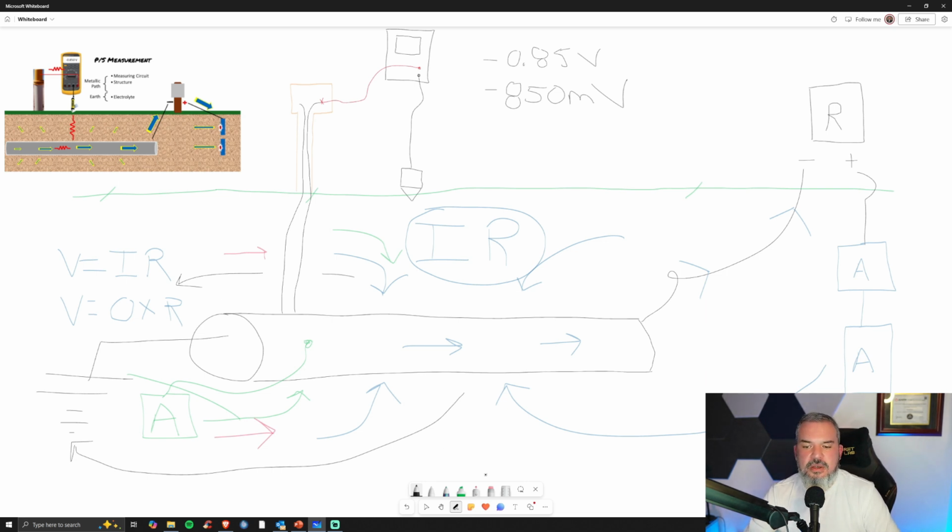So what we can do, there's a couple things. All right. There's no perfect way. I'm sorry, there's not a perfect way, but there's a couple things you can do. Okay. I'm a fan of installing, I got to find another color. Let's go purple. So what if we installed a drop tube? And that's typically PVC. And we may fill it up with soil here and perforate the bottom.